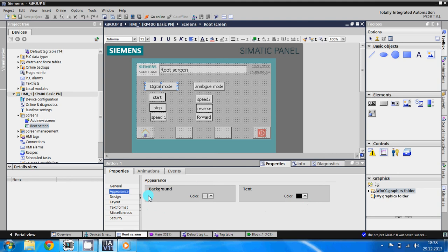And what's the most important thing in here is, for example, when we're using this button for implementing something, for example giving input to PLC, when we press a button from HMI, it works in fractions of seconds using the falling and rising edges of the signal.